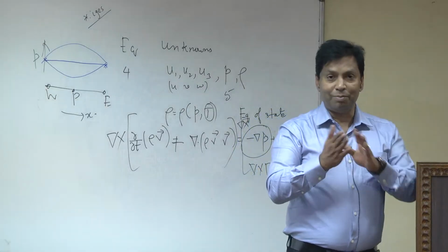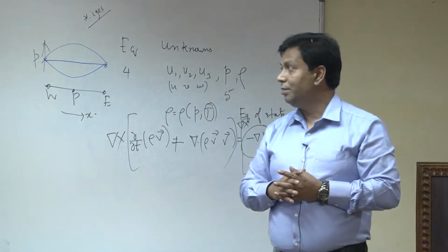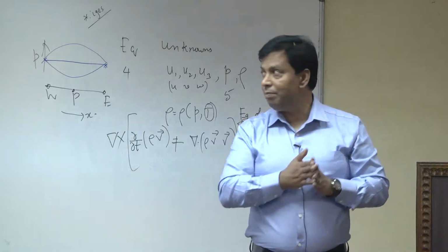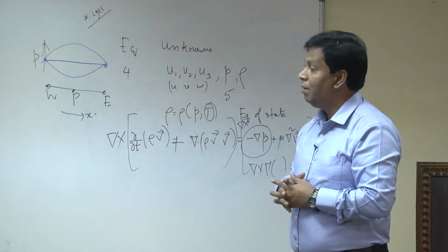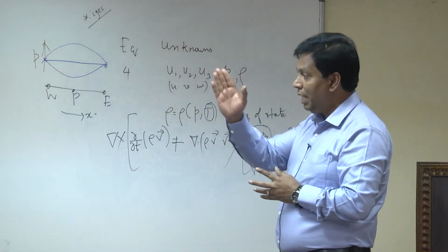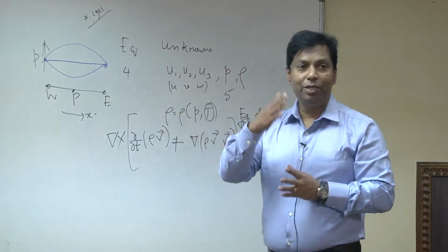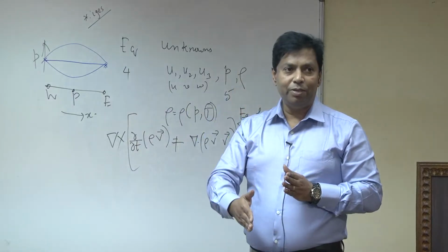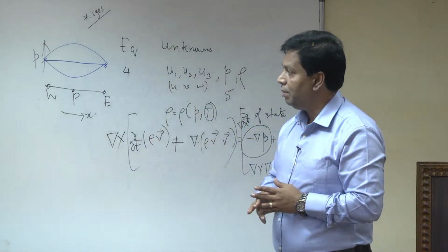So, sometimes the flow actually changes and is not symmetric, but this kind of symmetry you can use the symmetry boundary condition, axis boundary condition, or periodic. If the same results come every interval, you can apply the periodic boundary condition, and it will be the same.